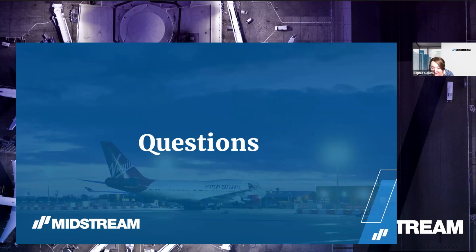When calculating the maintenance factor, will the lux level increase or decrease if we increase the maintenance factor? When you increase the maintenance factor, meaning you get closer to 1, your first day light levels on the ground will be very close to what you have on paper. When that maintenance factor is decreased, so we get closer to 0, it means that your light levels in real life will always be higher than the ones you have on paper. So the light levels that you read on paper are a decreased version of what you have in real life, according to whatever the maintenance factor was.